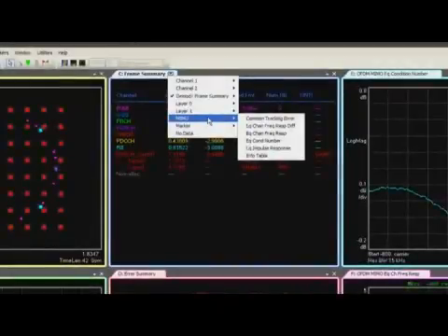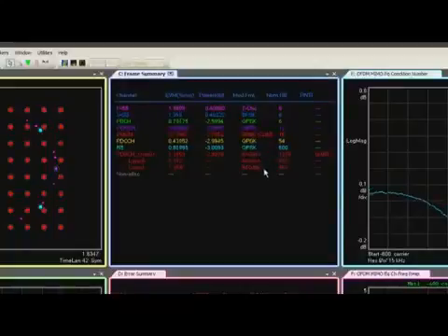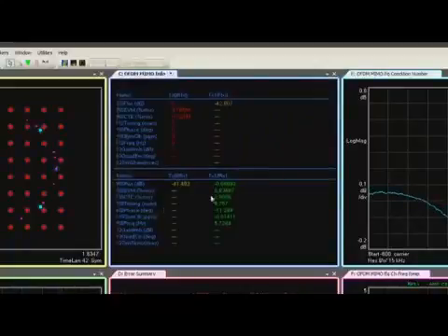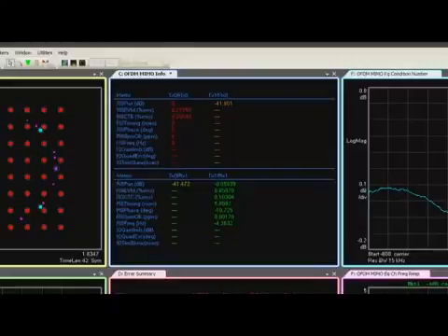This menu provides access to measurement results related specifically to spatial multiplexing. For example, this information table shows the characteristics of the various direct and cross-coupled paths in the system. This is useful for verifying the pre-coding matrix and for detecting unwanted cross-coupling between channels.